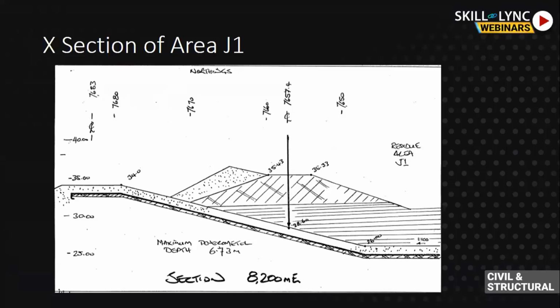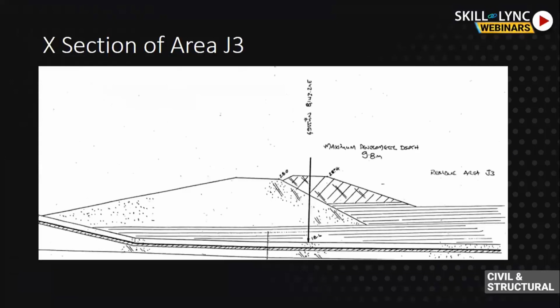When this was studied in the case of J3, we find that the dozer-compacted red mud is referred to as stiff silty clay to clay silt, and the mean qc was around 3 MPa, compared to 5 MPa in J1.